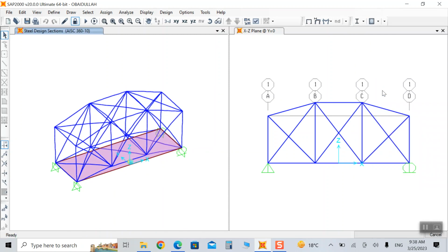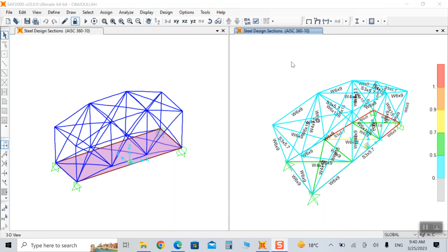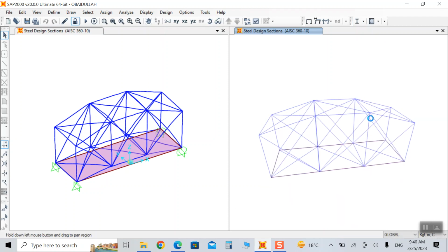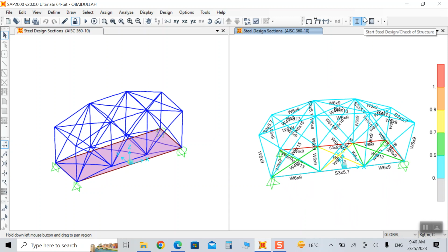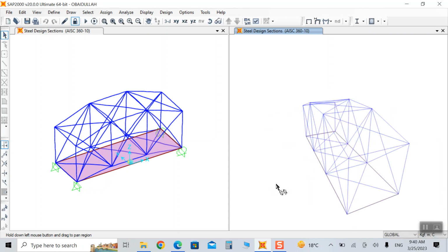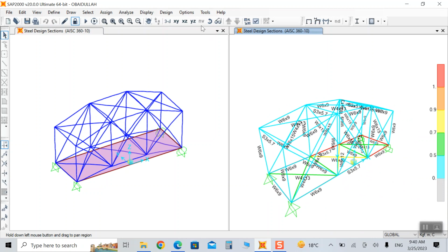design. Now if you see it is our design. In here one problem is that we cannot design for concrete and for steel at the same time. You have to do for concrete separately in a new file and for steel separately. Okay, it is our design.